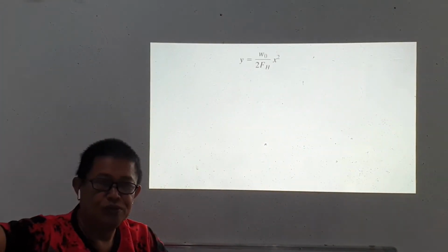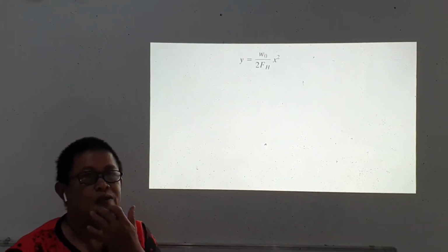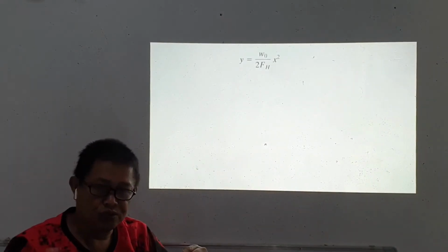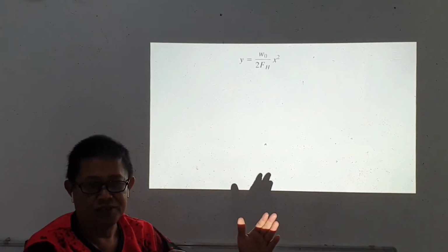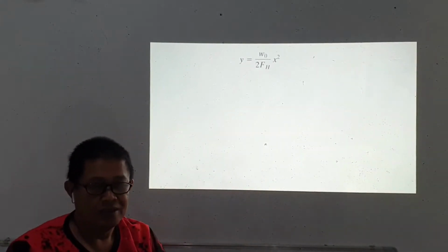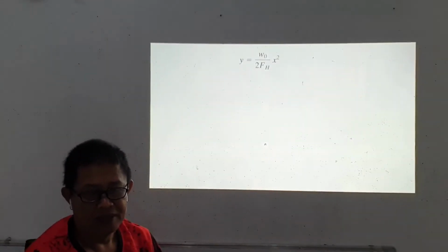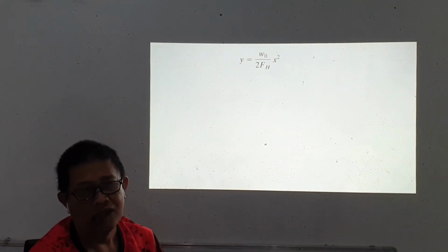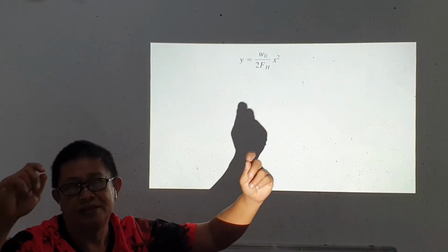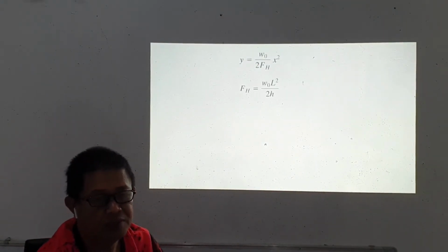So from the lowest point to the support. So L there should be 1/2 of the span. Or if the supports are not at the same level, then L is the distance from the lowest point to the support, and from the lowest point to the other support. And they might vary, because if they are not located at the same level, then the distance between the supports and the origin, or Y0, would be different. They are only equal if the supports of the cable are at the same level, the same vertical elevation. Okay, so these are the equations that Hibbeler is giving us.